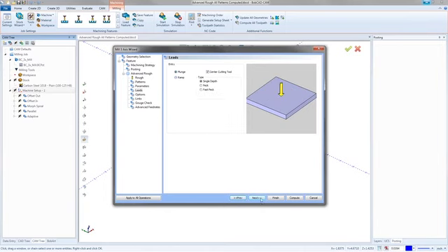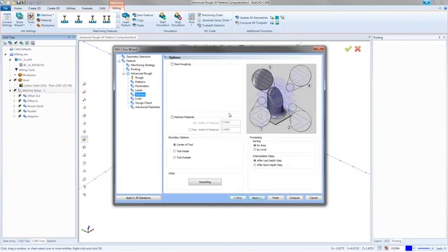So right here, I'll just plunge in. With the plunge on any feature, you can do a single depth, you can peck, or you can fast peck. So you just choose what you want and then hit next. The options, not too much am I going to play around with on here. I'm intentionally not using the rest roughing because I haven't come in with a larger tool to clean up anything else, but I could if I wanted to, just because some of the corners on this part are a little small. But then right here, we have the machine flatlands.